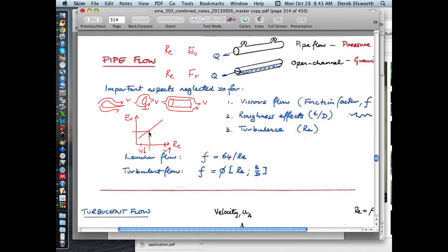Force on a plane, we're typically interested in lift mainly, but also drag, to calculate whether you could lift a certain weight off the ground. You're interested to make sure that the force applied on this dish is not so big that the moment snaps the pole. And this is really kind of like a wing. In some respects, it's just an external flow. In this case, you can imagine that if you're thinking not in terms of lift, this is the better example, if you look at the pressure that's applied on the front of here and the pressure that's applied on the back of here. I'm not trying to make this look like a funny face, but there's a change in pressure between back and front.